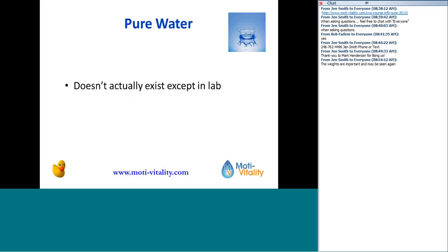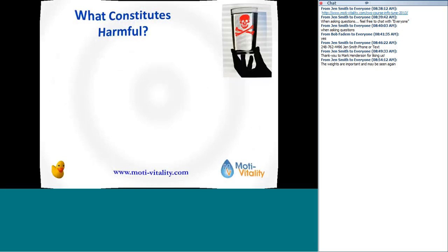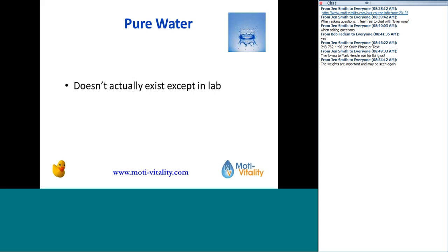Pure water actually doesn't exist outside of a lab, and this is kind of important too, because we'll talk about this when we get into the Code of Ethics, the WQA ethics, which is way back towards the end of the course. We hear people in our industry talk about water purifiers, and well, reverse osmosis, that's pure water. It's actually not. There's a very strict definition of pure, but pure water does not exist except in a lab, and that's because water is the universal solvent. It tries to dissolve pretty much everything it touches.